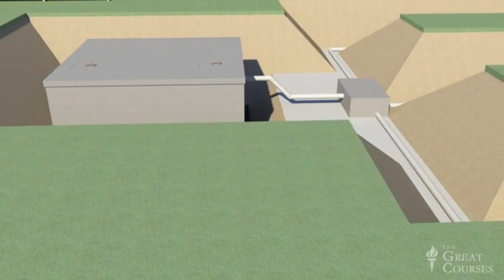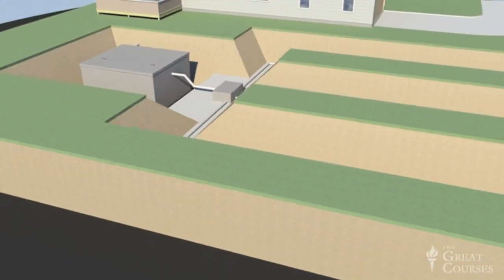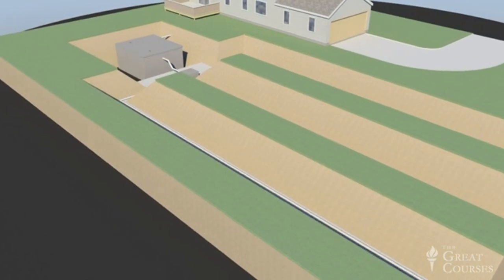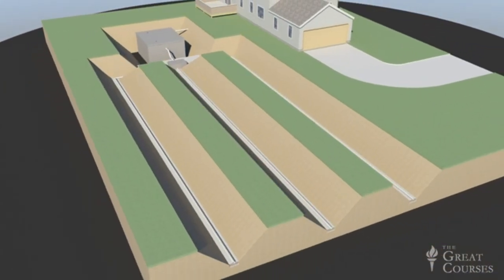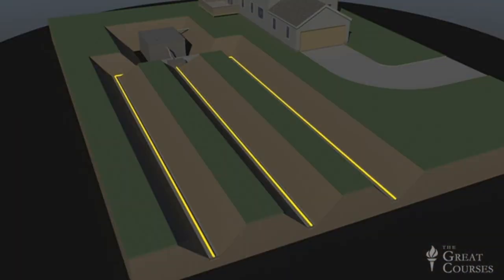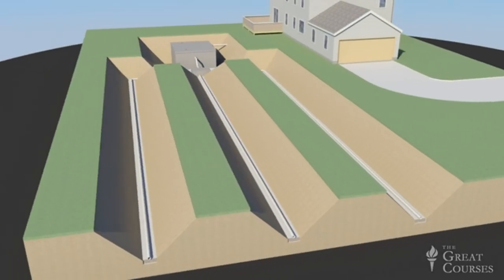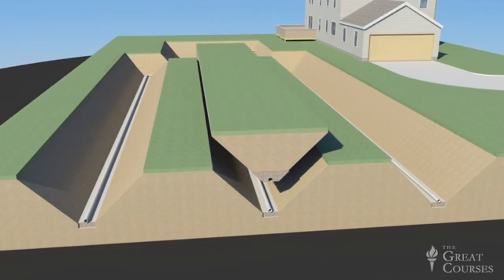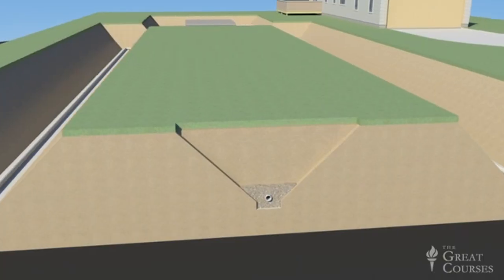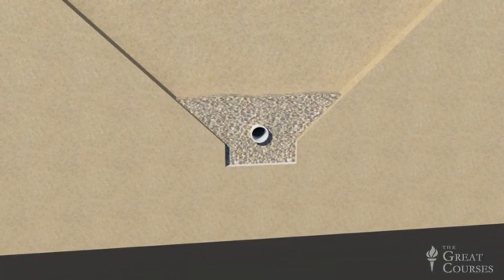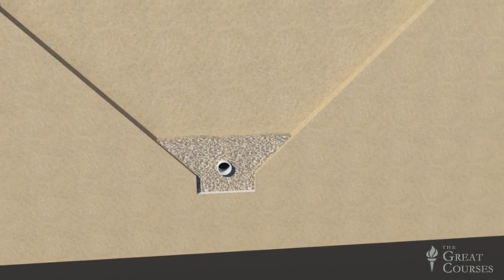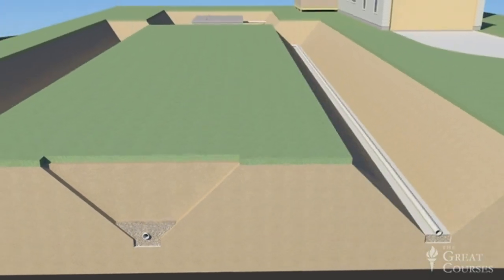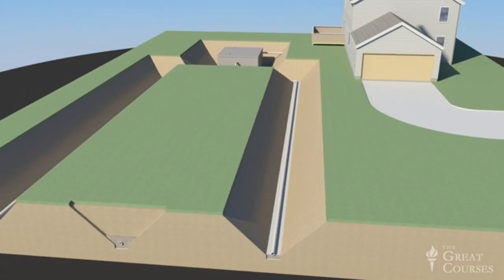Wastewater flowing out of the septic tank has lost much of its suspended solid material, but is still loaded with organic compounds, which must be removed by the drain field, a series of perforated plastic pipes up to 100 feet long, placed inside a gently sloping trench surrounded by a bed of crushed stone and covered over with soil. Wastewater flows through these perforated pipes, and then it seeps out through the bed of stone and into the soil below. The stone accumulates a thin layer of those same helpful microorganisms that feed on organic material, and the combined